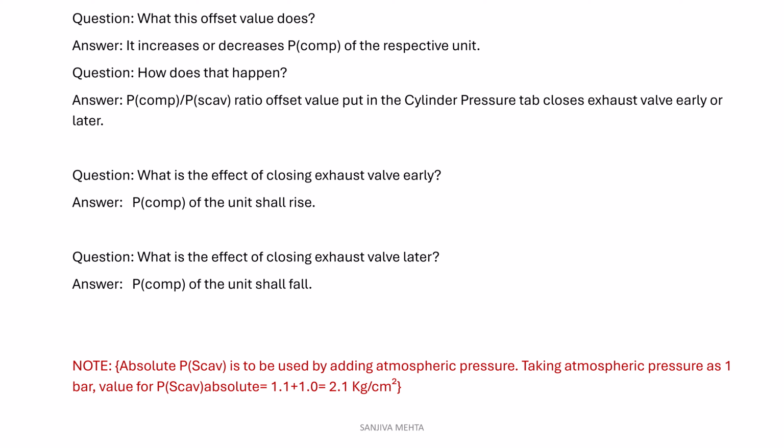Closing the exhaust valve a little early in the cycle, what will happen? The compression pressure will rise. Were you ever able to even think of adjusting the compression pressure like this, or adjusting your exhaust valve closing time? Never. A new kind of thinking has to come into the minds of marine engineers. That's why I suggest right from the beginning to do this course. Even juniors should do it; the company should actually send them. If you need a good engineer, you need to train them.